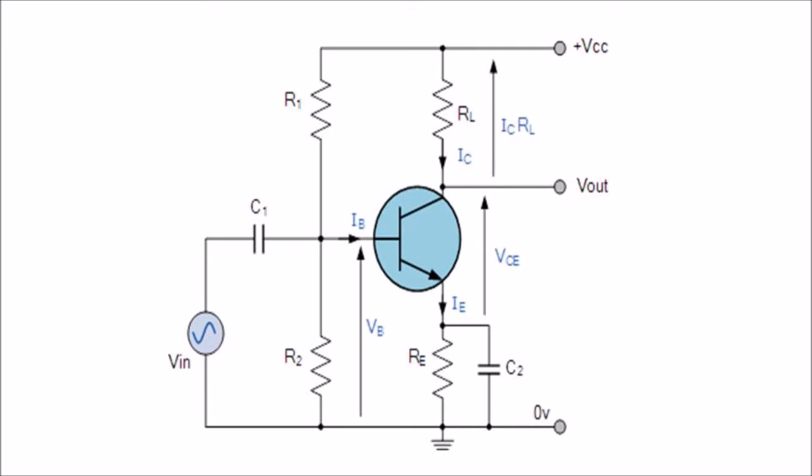The voltage divider biasing is commonly used in the design of bipolar junction amplifier circuits. This method of biasing the transistor greatly reduces the effect of varying beta by holding the base bias at a constant steady voltage level, allowing for best stability.